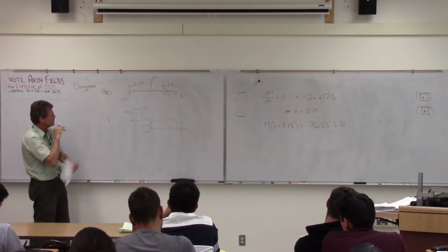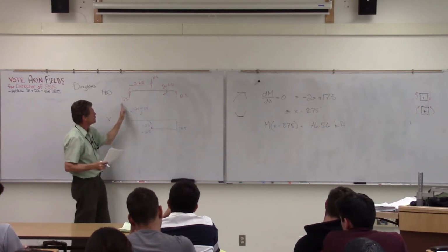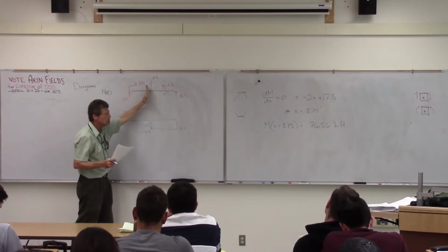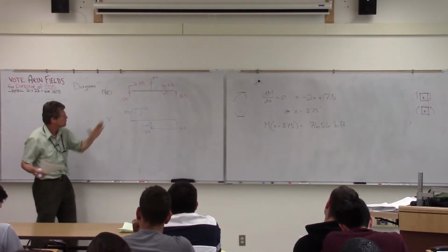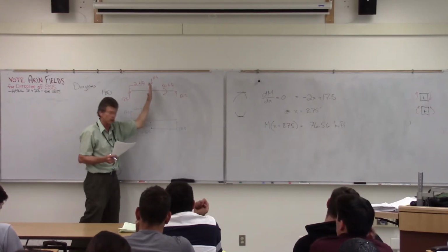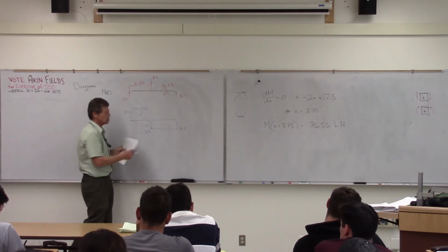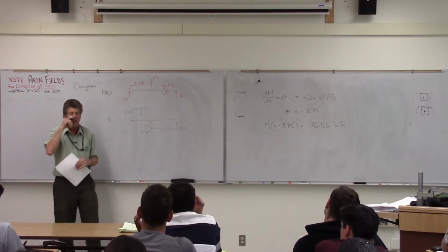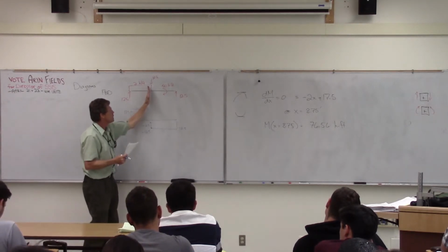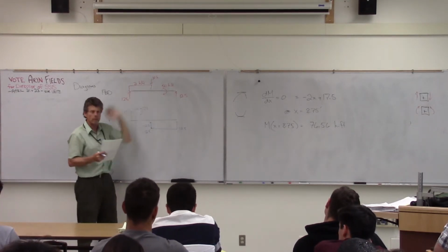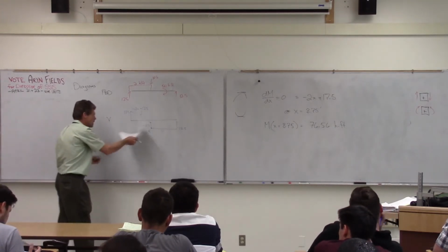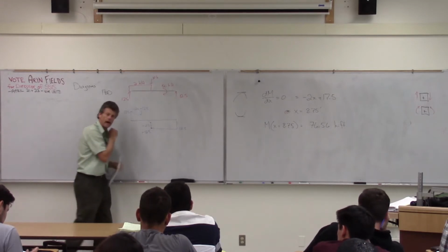Okay. When we get to this point there, as we go across here, we started off at 17.5, but notice in terms of my vertical equilibrium, as I move across there, that 2 kips per foot is increasing, increasing, increasing, to the point where it actually drives me down into the negative range, minus 2.5. And then when I jump just across that 10, there's that big 10 kip jump. Vertical equilibrium, well, I've got to account for it. So my shear diagram will show that.